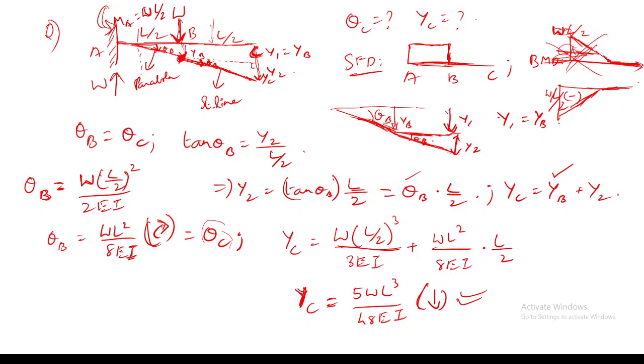Yes, we have done this for simply supported beams, but I think you were telling that the sign convention was valid only for simply supported and cantilever offers a different sign convention. No. See, for example, here the bending moment diagram is always drawn by this sign convention: left clockwise, right anti-clockwise.